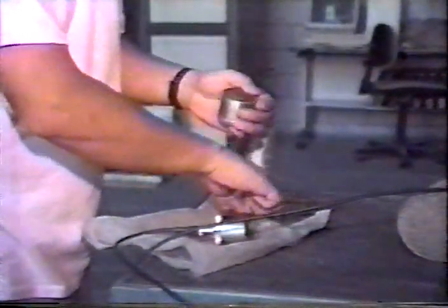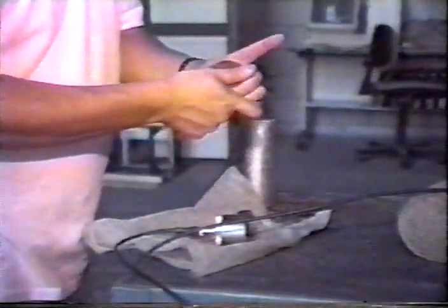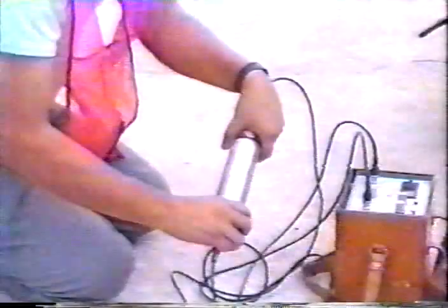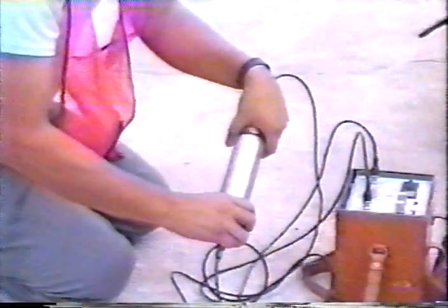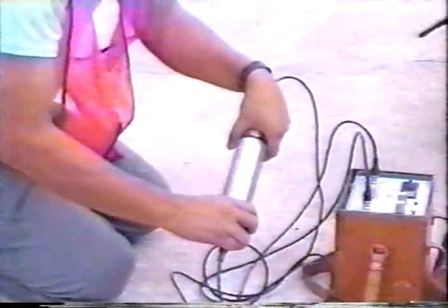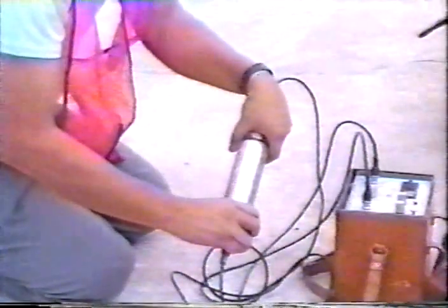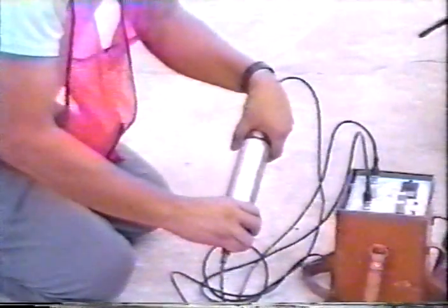A thin layer of grease or sealant is commonly applied to the transducer face to assure good acoustic coupling between it and the concrete surface. The equipment should be calibrated frequently using the standard reference bar supplied. Calibration is necessary since transit time may be influenced by transducer cable length, thickness of coupling sealant, and contact pressure. Using the zero control, the time display is set to the transit time stamped on the calibration standard.